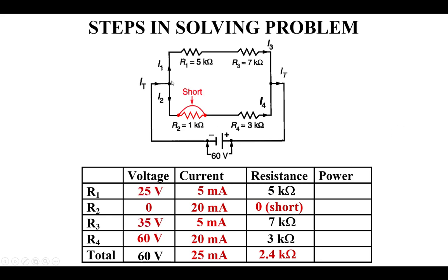And again, you see that if you calculate one of these currents and you know what the total current was, this is whatever's left. You can just subtract this from the total to get this. Again, do it the way that seems the easiest, what comes to your mind the easiest. That's the right way to do it.